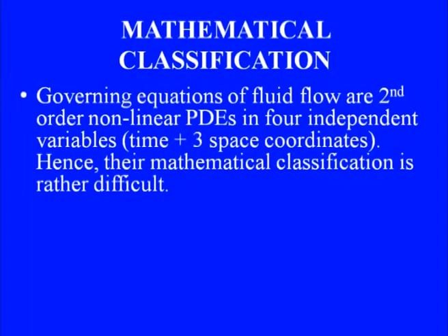Now before we can proceed with the numerical solution, we have to grapple with a few issues, that is, what our choice of the governing equations should be. That will depend on the physical phenomena, and based on the physical situations, we can derive, the way we have learnt, our governing equations, that is the basic conservation laws which will give us the equations for continuity, momentum and energy. But we should know the nature of these equations, because that will dictate the choice of the numerical schemes which we can use.